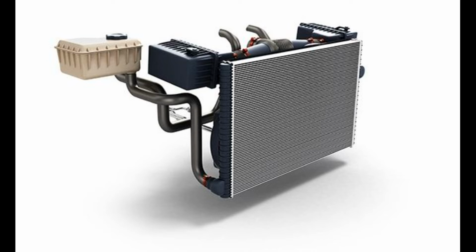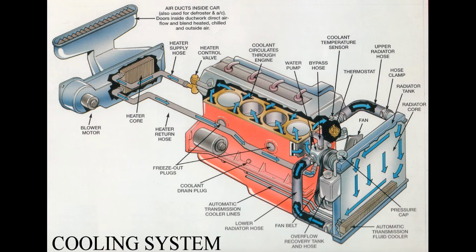So let's start with the water pump, and let's say the engine just started and it's cold. The water pump inlet and outlet are connected to the engine with the help of rubber hoses. We have a thermostat mounted in the path of the outlet to the engine, so water is pumped by this radial pump through the thermostat into the engine water vents. The thermostat does not allow the water to go into the radiator circuit while the engine is at low temperature, and water comes back to the pump through the outlet hose.